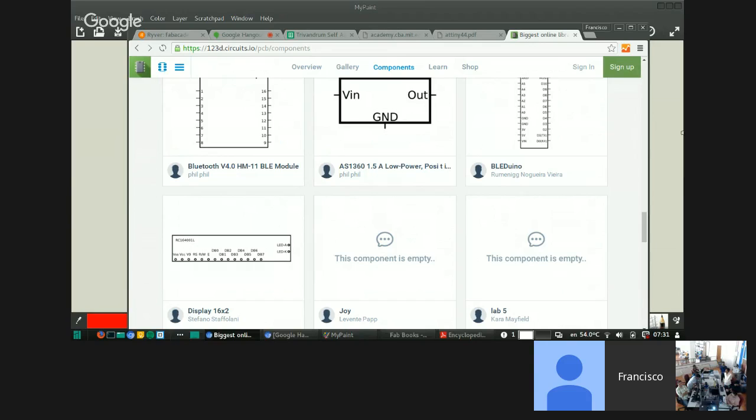So what you do is you put your numbers, like suppose you are designing a DC-DC converter, so you just give what should be your input range, what should be your output range, what kind of power you are drawing. Then they give a lot of simulation results, like efficiency over power draw, a lot of things.